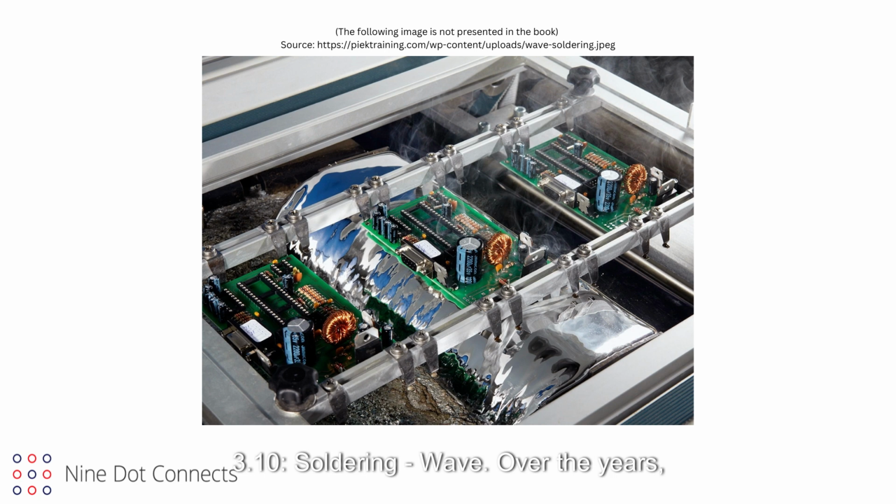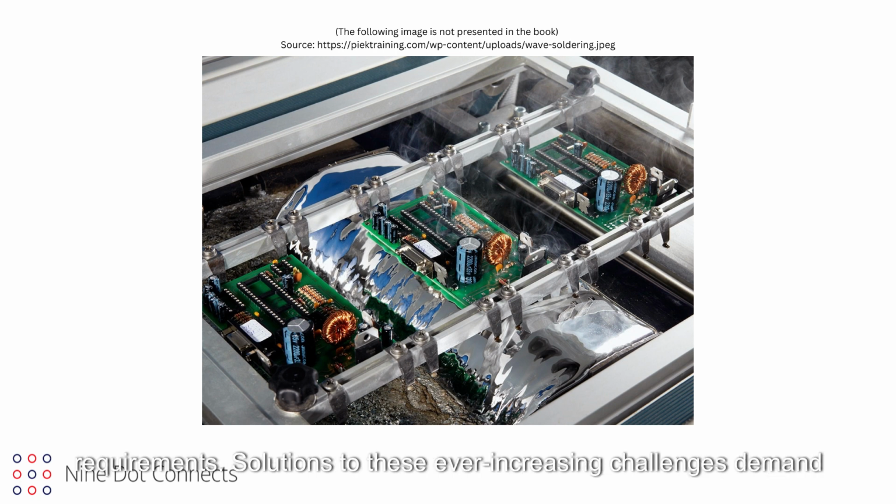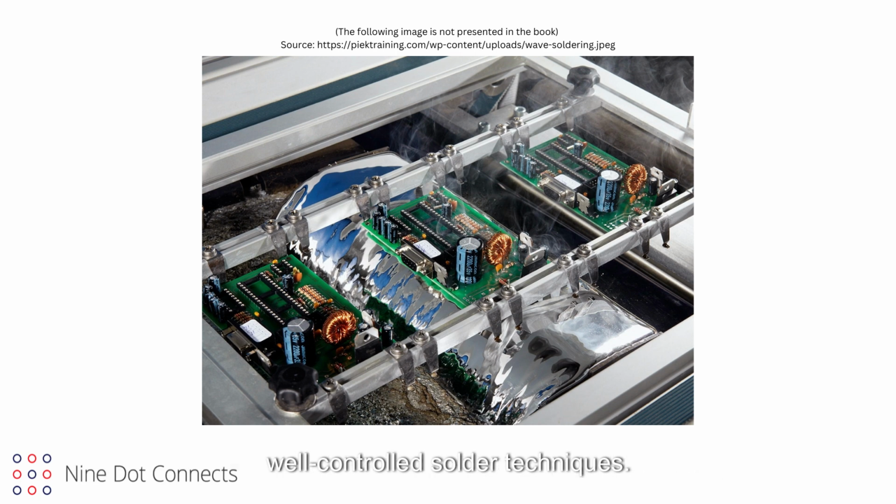3.10 Soldering, wave. Over the years, components have not only become smaller, but there are more types of SMDs being used than ever before, and many with specific assembly requirements. Solutions to these ever-increasing challenges demand well-controlled solder techniques. Even with these new demands, the venerable wave, or flow, soldering technique is still a viable process.